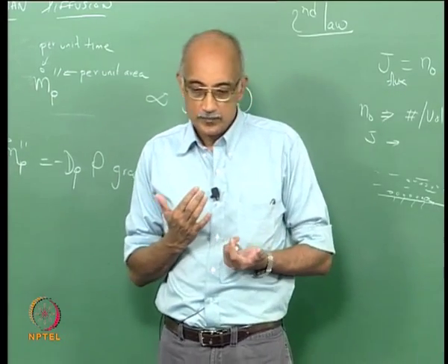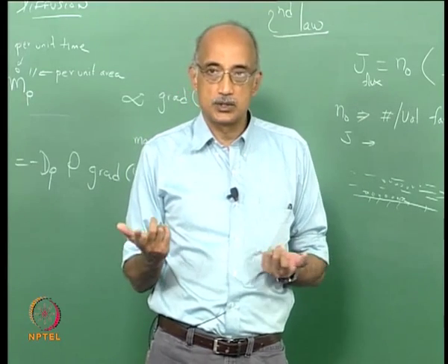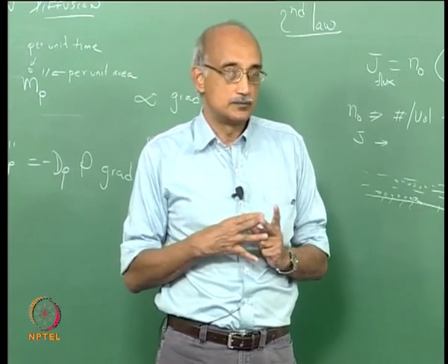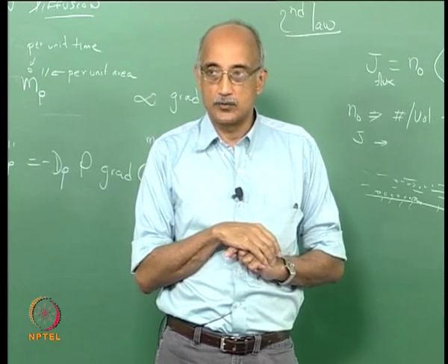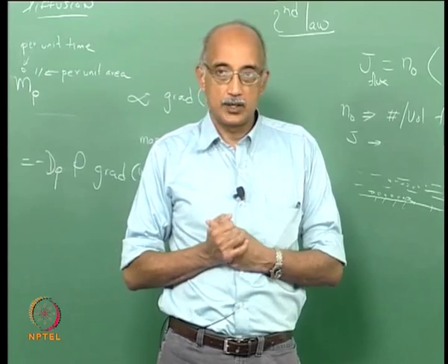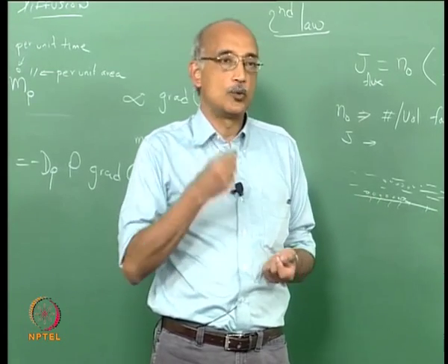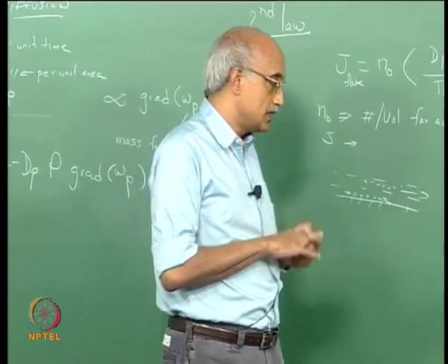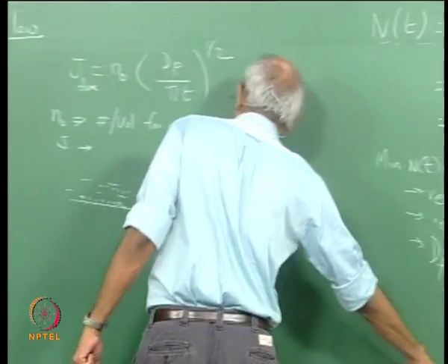Now if the charging of the particles happens by a random mechanism of collision with ions present in the atmosphere, then the charge distribution follows a Boltzmann distribution. So the net charge on an assembly or collection of particles may be 0. However, the individual particles will carry positive and negative charges depending on what ions or electrons they have collided with. On the other hand, if you have intentionally charged a set of particles, obviously they will not have a Boltzmann distribution. They won't have an equilibrium distribution that results in a net 0 value, but they will have an overall positive charge or overall negative charge depending on the charging field that you have applied to the particles. Now under these conditions you set up a force which we have actually looked at in the context of particle to surface interactions, and that is the Coulombic force.